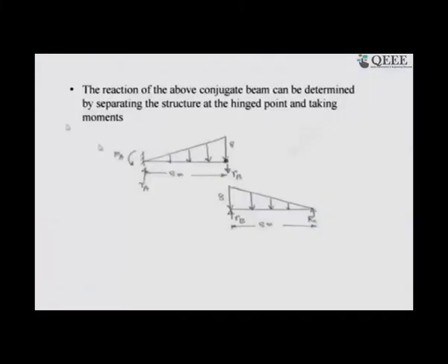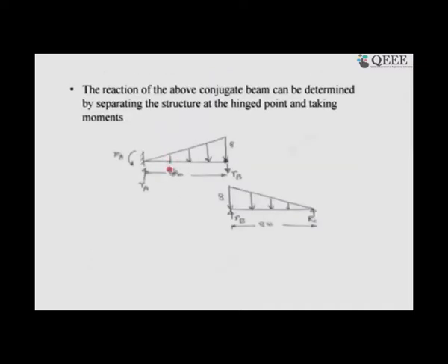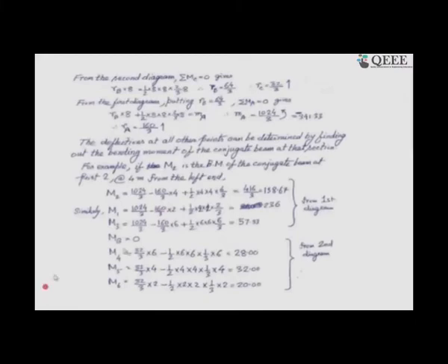Now, come to our slide, what we are exactly doing. Here in the indeterminate structure we are with the conjugate beam method, and then it's simple. I will not discuss anymore. You just sit at a section, here, here, here, and then come from the right probably, at different sections, and from the conjugate beam you find out the bending moment of that conjugate beam at those sections, and you are ready with the deformations or the deflections.